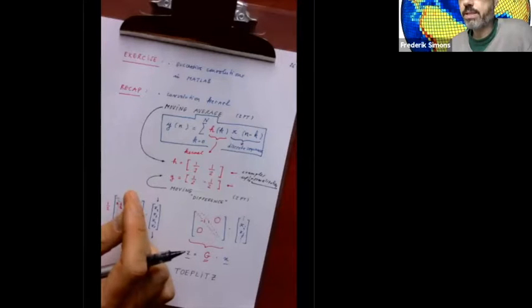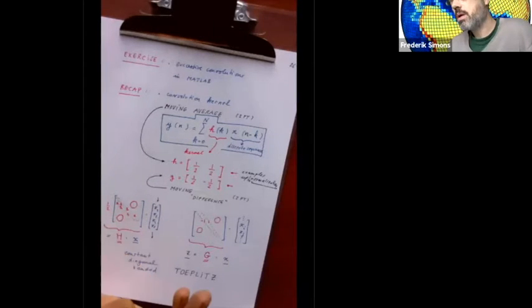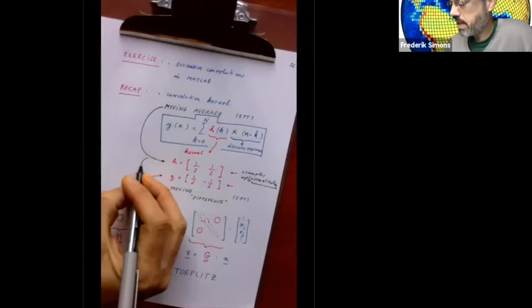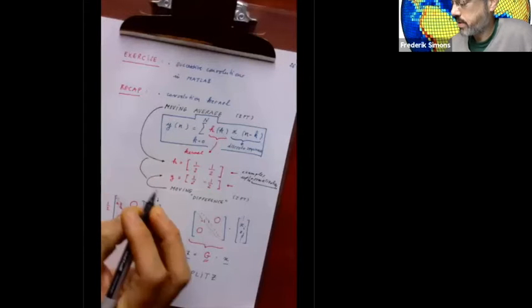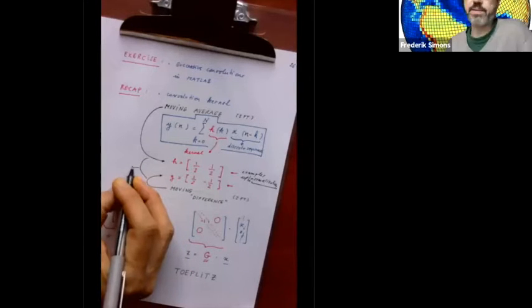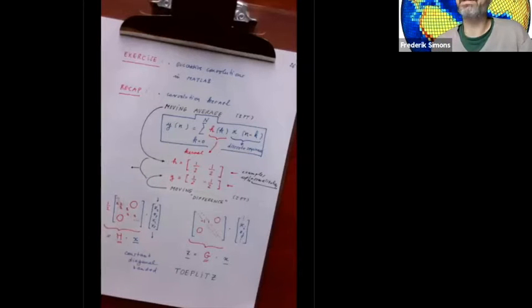The question is as follows: can you reconstruct a signal if instead of the x's, you're getting the moving averages and differences? Is there any information lost if you have both those outputs, and can you get x back? And if it's a coding job, they'll ask you, can you write a little algorithm that does that by replacement of elements without requiring any more memory? And so the answer is yes, and it's going to take us too far, or rather I'll return to it at some point. But it turns out that if you have a signal and you keep the moving averages and differences, you can indeed completely reconstruct it.